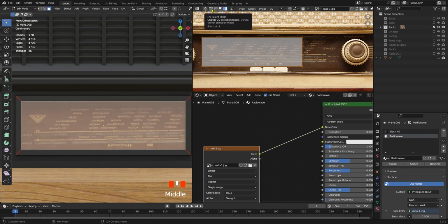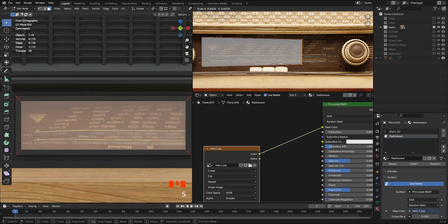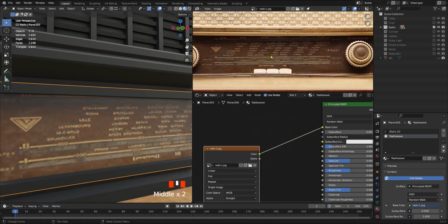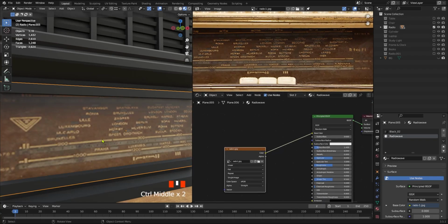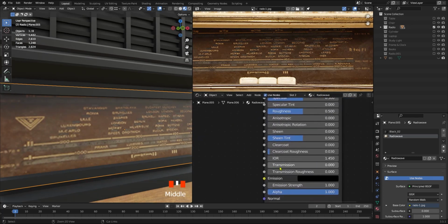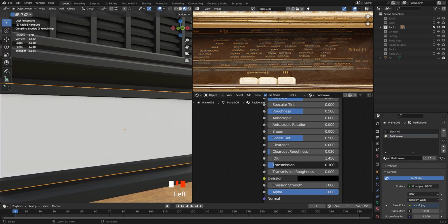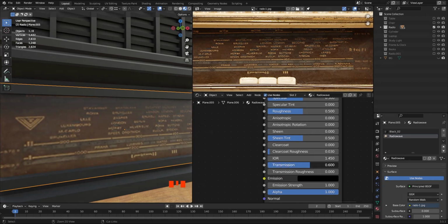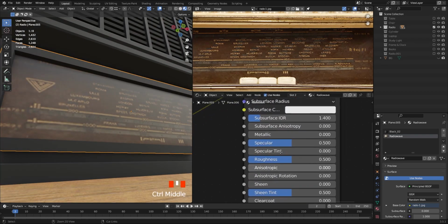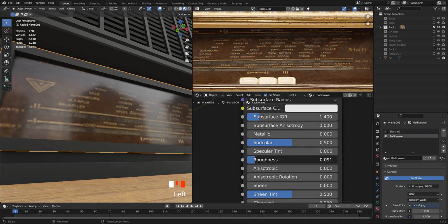We need to switch to vertex. Scale these two vertices down slightly. And its resolution is too low. I'm going to do some stuff to avoid it from happening. Set the transmission up to 5 or 6. Decrease its roughness. The less it is, the shinier it becomes.